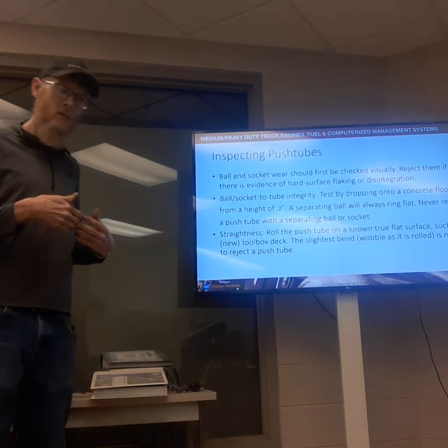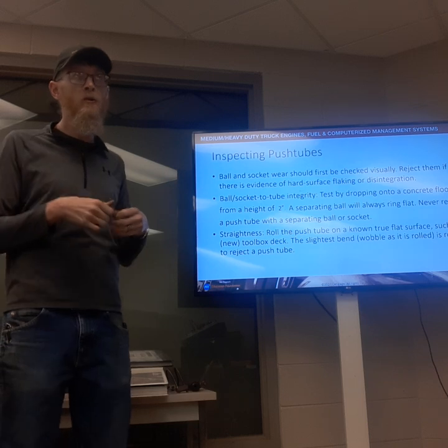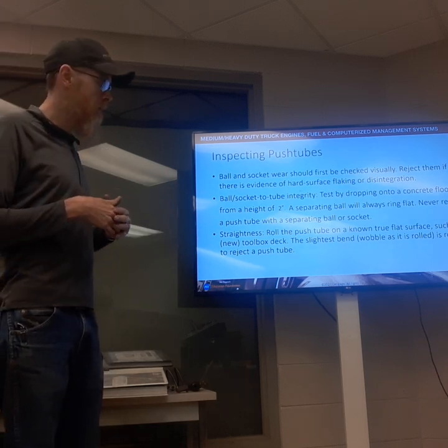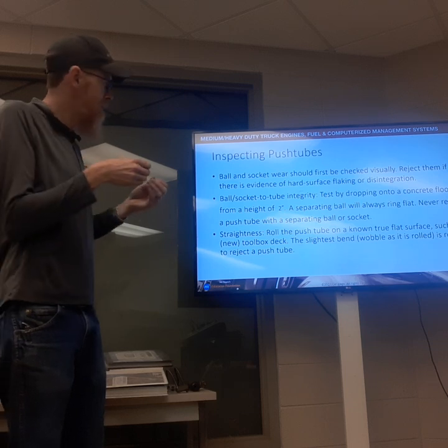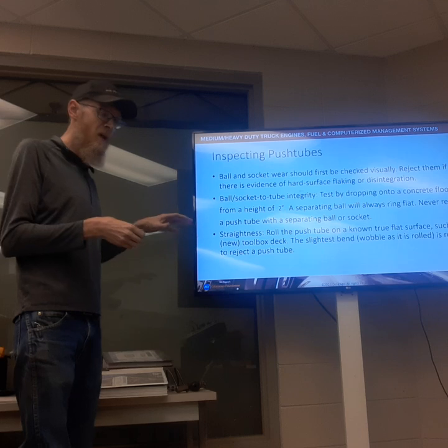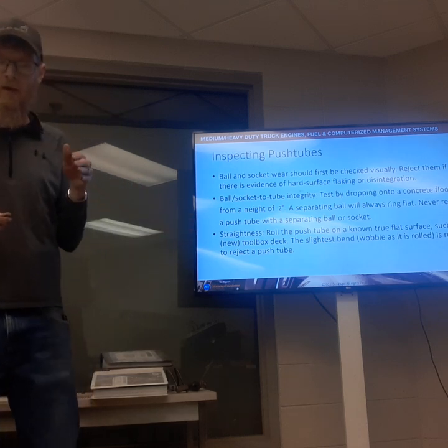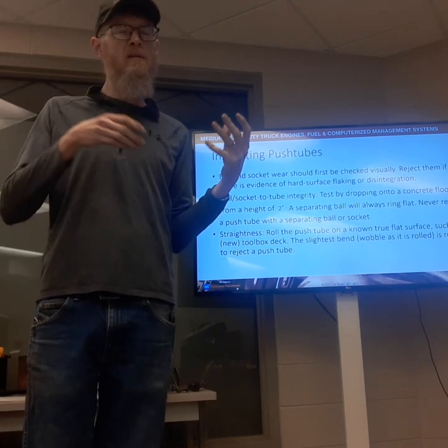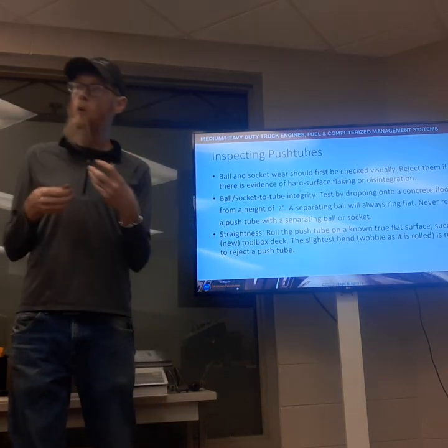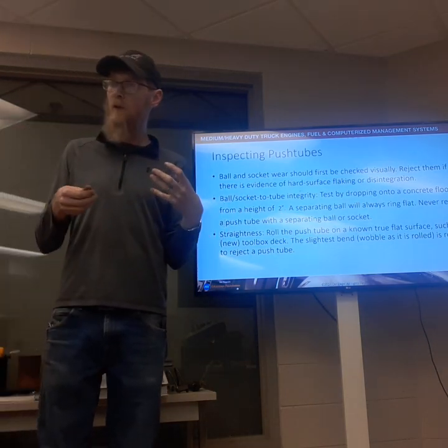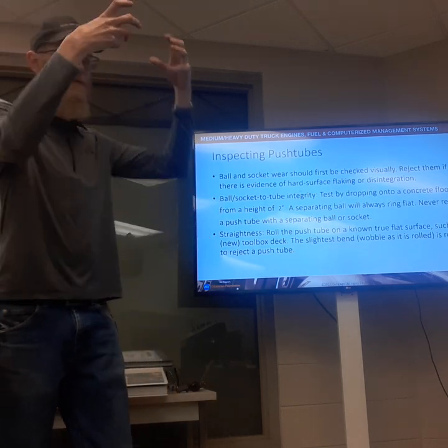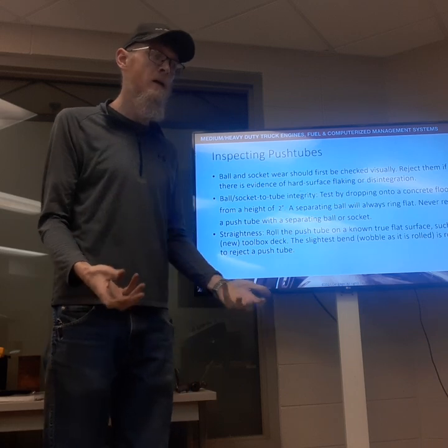Again, there should be oil, or lube oil, between all these components. Ultimately, the only time any of these valve train components should be in contact with one another is during startup, where the engine has been sitting and there's no oil pressure from the lube oil pump, and that oil has, by gravity, drained back down to the oil sump.